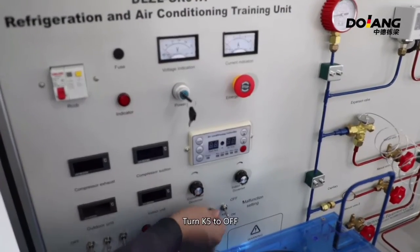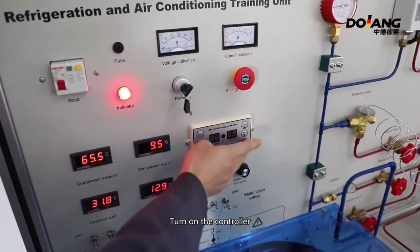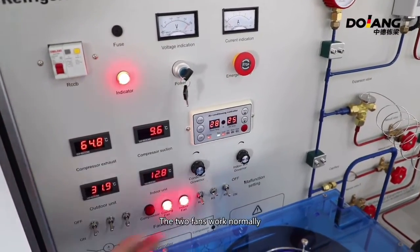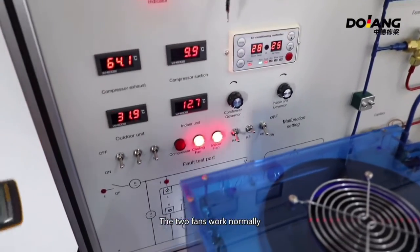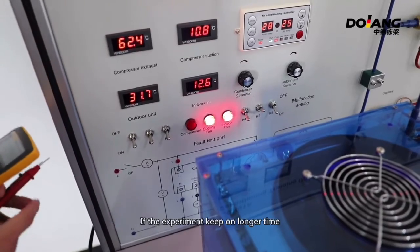Now do the fifth fault experiment. Turn K5 to off. Turn on the circuit breaker. Turn on the key switch. Turn on the controller. The two fans work normally, but the compressor fan doesn't run.